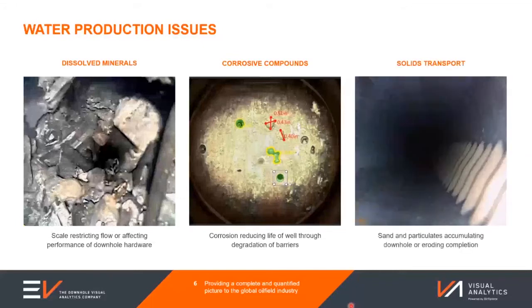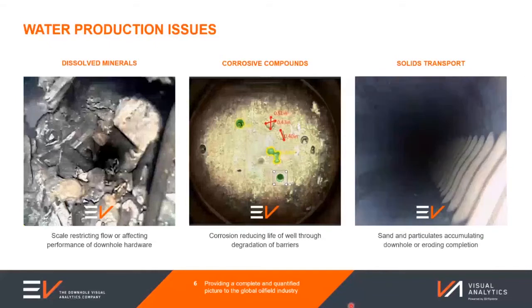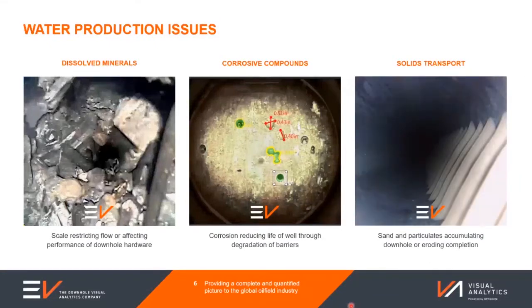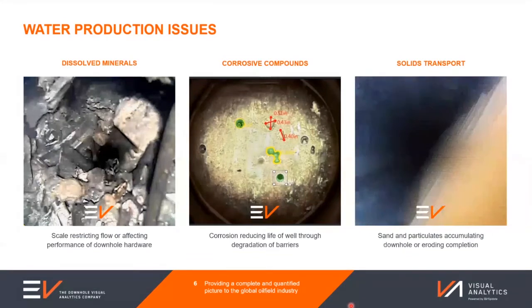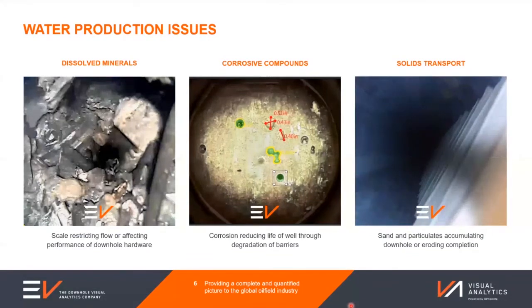And it's not just dissolved content that we need to worry about. In a lot of cases, a breakthrough of water can bring with it free particulates, particularly sand grains and fines, and these can have an incredibly erosive effect on the well itself and some of the surface structures. Or if the flow rate is insufficient to lift the sand or solids to surface, then they'll accumulate downhole, eventually choking off production and potentially killing the well. So again, it's not just directly the water, but sometimes it can be the associated problems that cause us headaches as well.